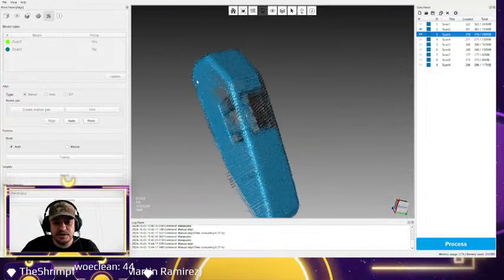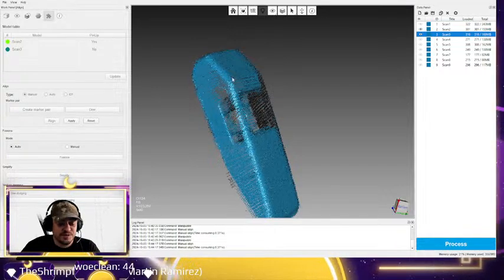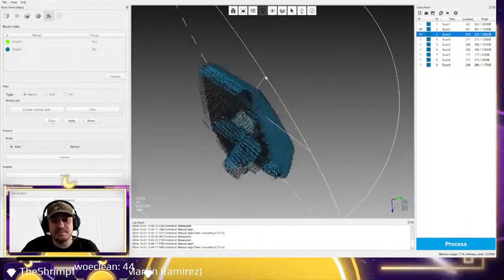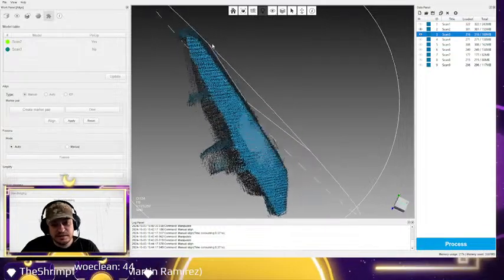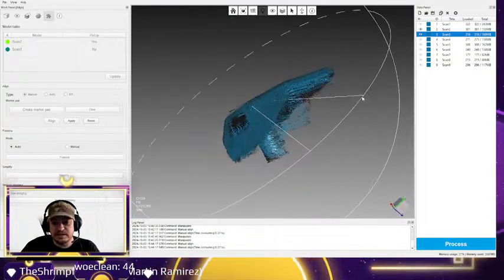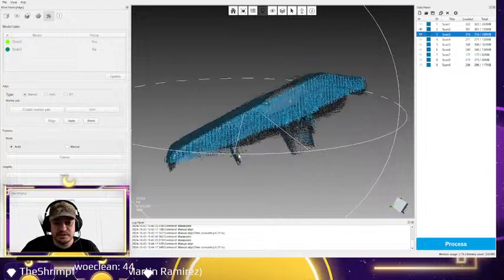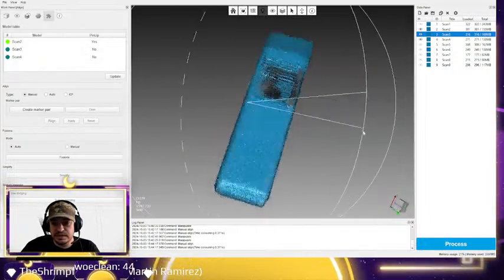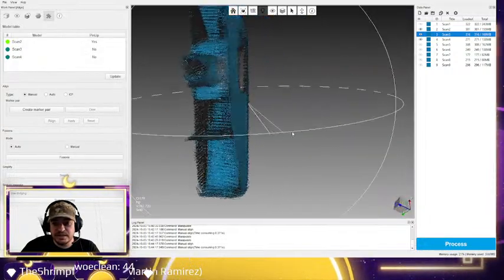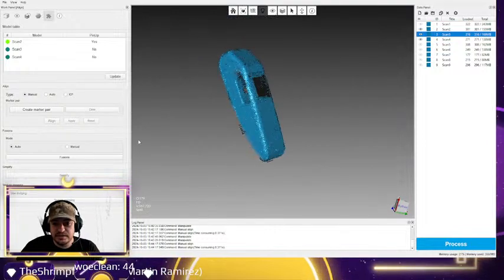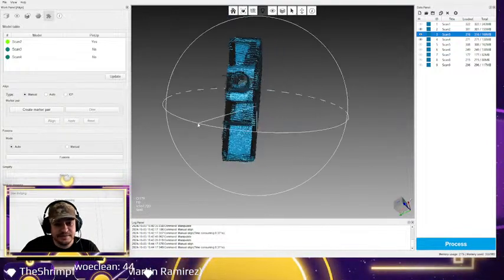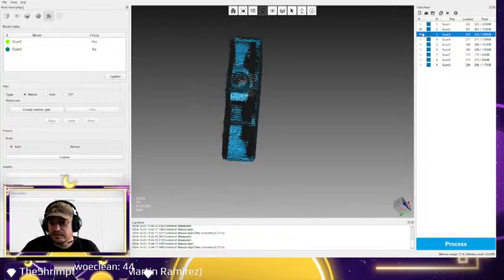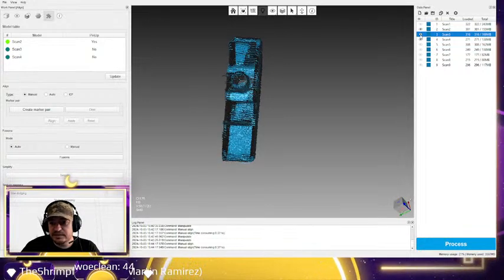If you focus all of your line points in a small area and you go to align it, those points may touch, but the rest of the model might be all wonky. So that's one thing that you need to be wary of when you're doing this. So if you look at it, those three scans right there, all together, that's pretty good. Now we need to add a backside to it.